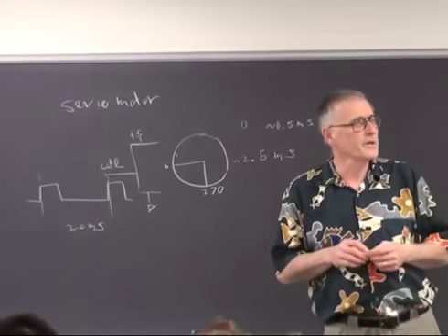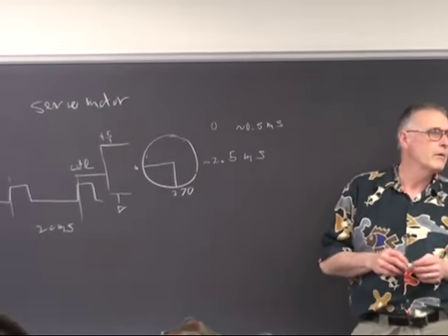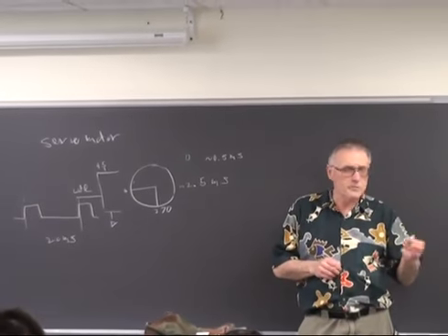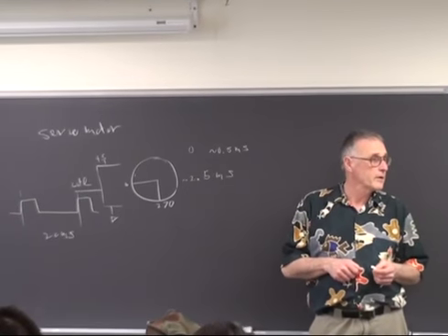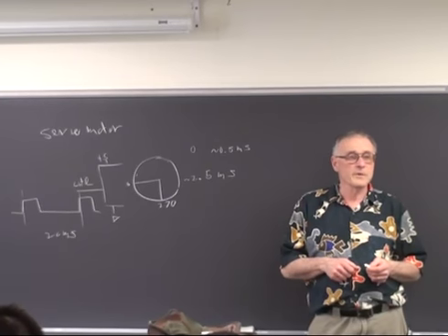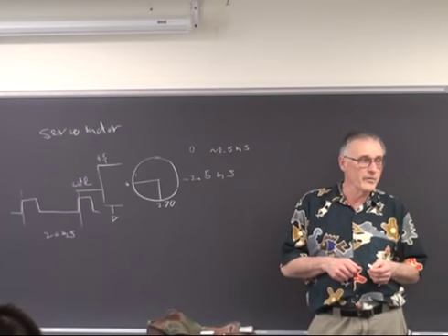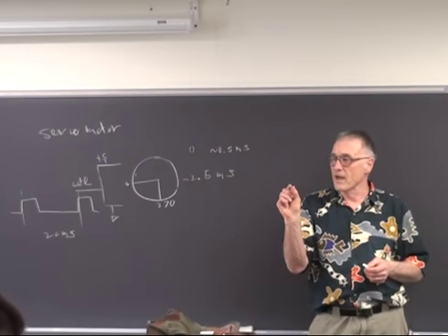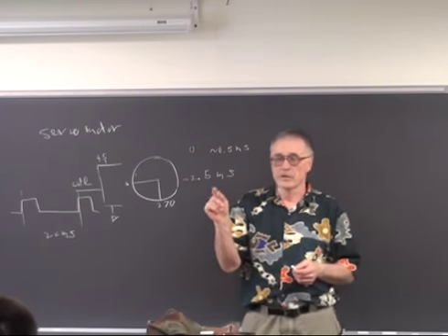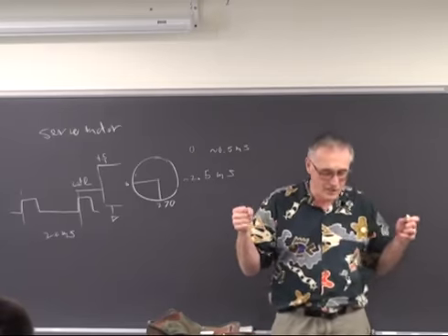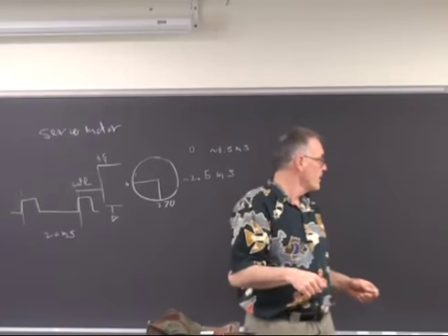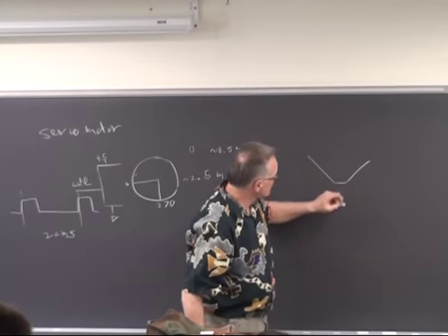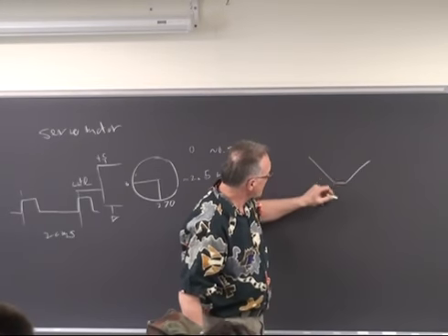What other kind of actuators can you think of? Linear actuators, like for instance a loudspeaker. A loudspeaker is a high bandwidth linear actuator, relatively small travel. You typically only get a few millimeters unless you have some gigantic bass driver pushing a couple of centimeters. But the nice thing about speakers is that they are high bandwidth.